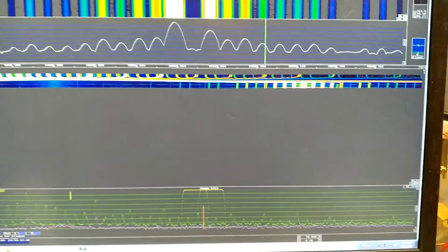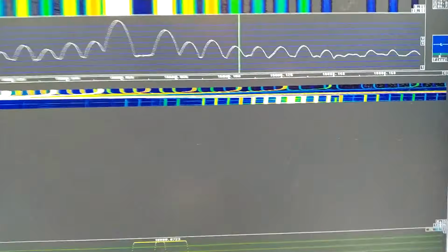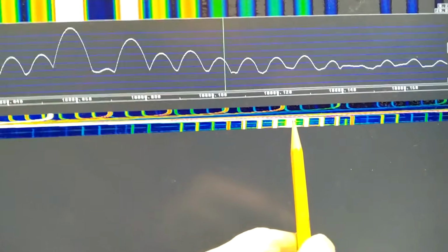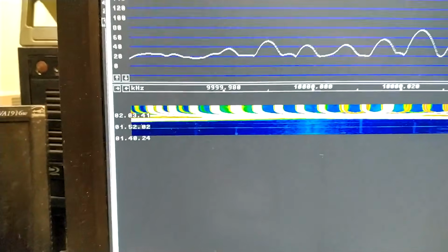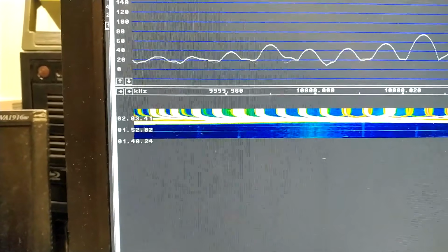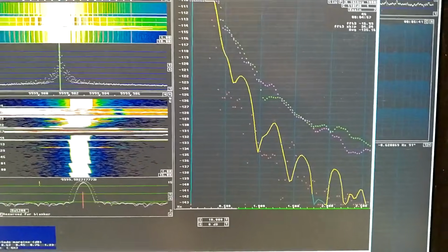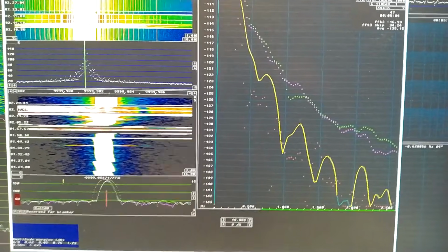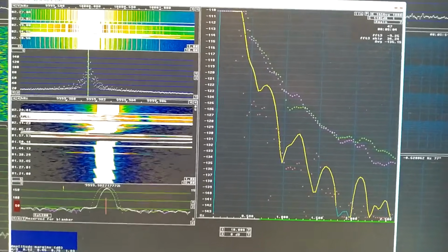I have changed parameters and connected the crystal oven again. Here is the phase noise when the oven was cold, and here when it is warm. And I don't think there is any real difference. Now, when the thermostat is back at the normal temperature, and I go back to look at both channels and for the phase noise, it looks perfectly normal.